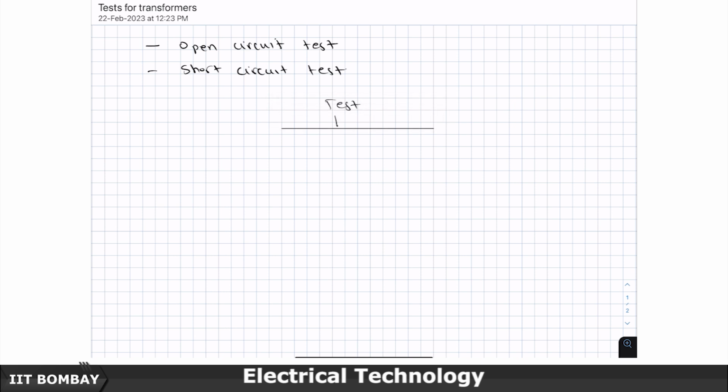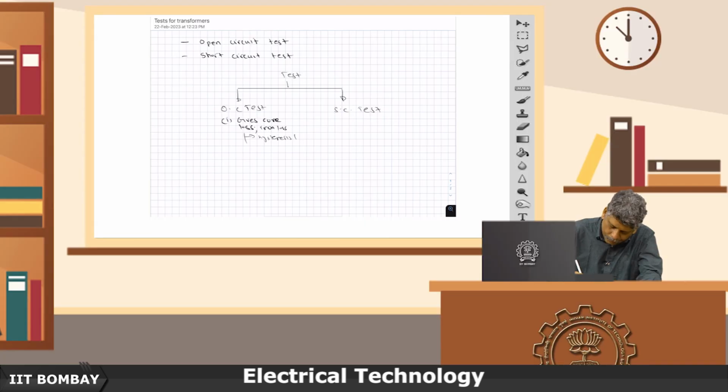is usually used to calculate... the main thing that this test does is give the core loss, which is basically also sometimes called iron loss, because iron is the predominant element in the core. Also, it gives you the sum of hysteresis loss plus eddy current